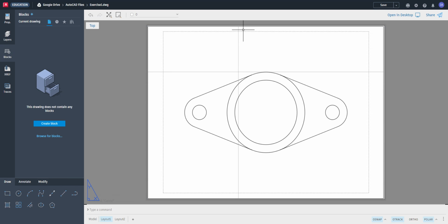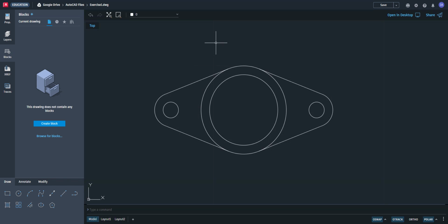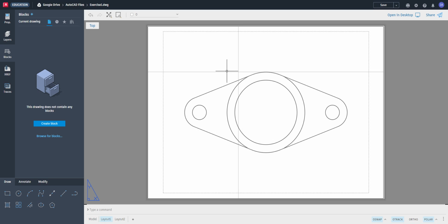This line that you see here, that's the grid. Okay, if you look at your model space, you're going to see a grid here. I don't know if you can see it from the video, but there's a grid here, and that's what's showing on your paper. It's not going to get printed. Okay, now this is not how big the drawing is. The drawing is only, if you remember, 8.55 from this small hole to this small hole is 8.55. Okay, so if we want to see the drawing as is, 8.55. Okay, you simply select the line of your viewport,